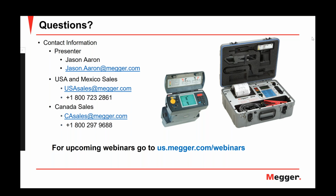All right, thanks, Sanket. Volney, the last battery string I measured had completely enclosed battery posts. What should be done if this is found? Yeah, that's a common situation. Some batteries will have an insulated cover or covers to insulate the strap and the post, so you don't have access to that. Some of them will have a little hole in the insulation where you can put the typical probe of a digital multimeter.